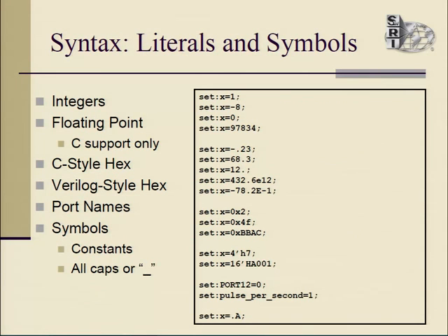The language supports a number of different literal types: integers, and floating point numbers for cases where you wish to target C code that don't make a lot of sense in Verilog. We support both C style and Verilog style hex values. You also see some examples of port names and symbols. We have the ability to define constants.